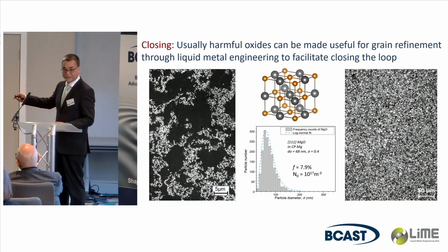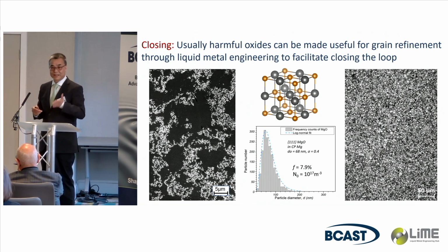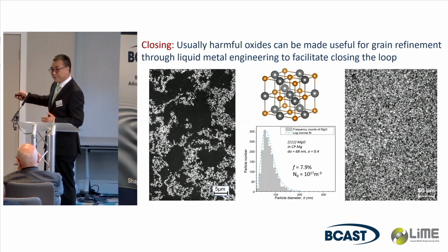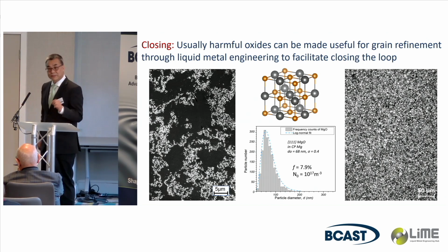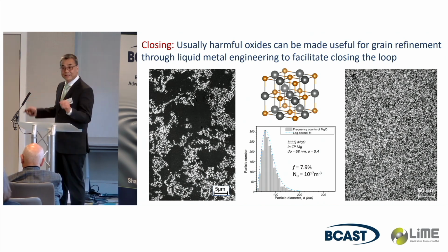They are nanoparticles. They stick together as an oxide film, and this can be dispersed. We developed a technology called high shear. Basically, you supply very high shear rates to the liquid metal. Very quickly, in a few minutes, they become very dispersed. And after dispersion, of course, the harmful effect of inclusions will be reduced or eliminated in some cases, as I'll demonstrate later on. And the first thing here, I see the inclusions are becoming very, very useful.